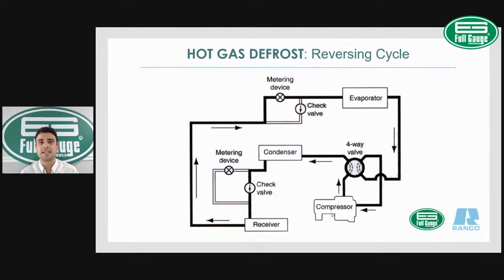In addition to that, there are other designs available. Three-way piping is one. There is one with a recirculation, a re-evaporator fan that will supplement evaporation to the cycle. So there are a number of designs that will be determined by the system manufacturer for the hot gas defrost.